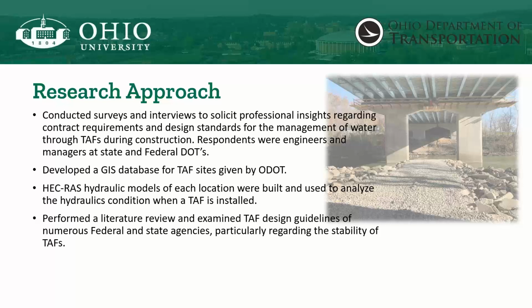Next, we developed a GIS database for all the TAF sites given by the department. At each site, we developed HEC-RAS 1D models. We just focused on 1D for now. We also built a TAF in the model just to see the hydraulics when the TAF is installed, and I'll show some results in later slides. We also performed a literature review, examining TAF design guidelines from numerous federal and state agencies, particularly regarding the stability of temporary access fills.